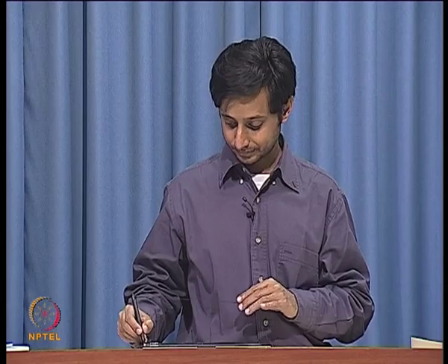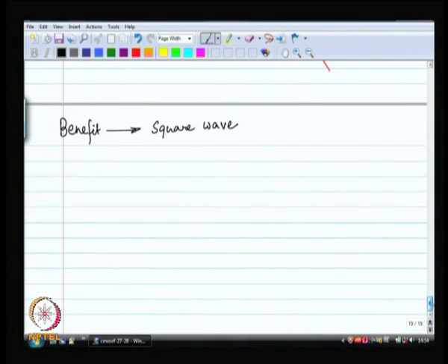all the noise is in the phase of the signal, the zero crossing in the signal, which basically means, coming back from statistical thermodynamics, that you get a 3 dB noise improvement over traditional sine wave signals. So, the noise power in a square wave is 3 dB less than the noise power in an equivalent sine wave. Wonderful. Okay, this is an extra benefit.